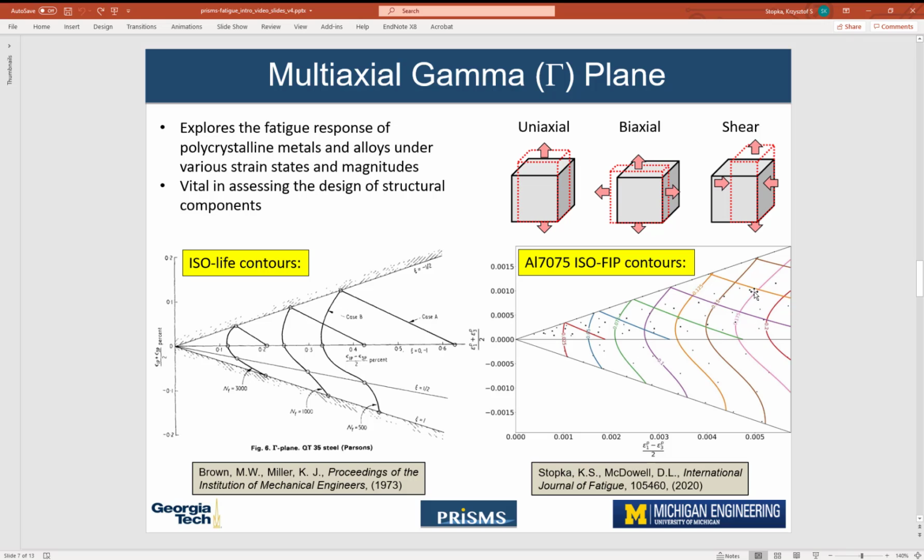Each one of these dots is one of the 95 folders. Then the response surface is the average value of the 10 highest FIPs. With the X and Y position on this plot, and with the Z, which is the average value of the 10 highest FIPs, we use that information in the Gaussian process regression model to interpolate between the points and create these iso-FIP contours.